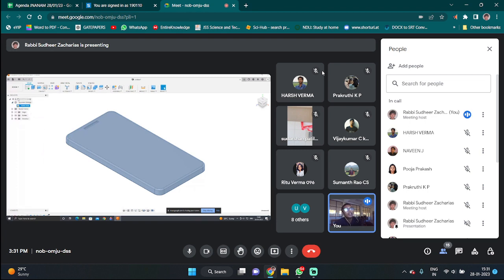Top left, under the browser option, you will have an option to change your units. So if you are comfortable with centimeters, you can change that by clicking the edit option. So I'll go back again. Document settings, with the screw symbol over there, click on it, and click on the arrow there. That will drop down to the units, whichever you want. After clicking, you can set it to millimeter, meter, or inch, as per your convenience.